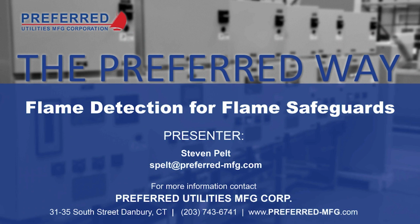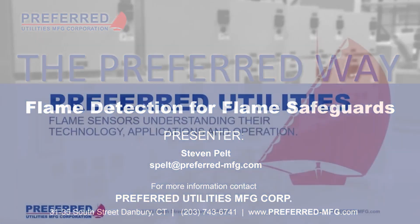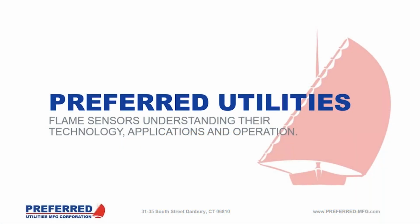This is on flame scanners, flame detectors, and flame sensors, if you will. Today I'm going to be discussing the different types and how they're used with flame safeguards in particular. The flame scanner is truly the main component of the flame safeguard system, and making sure that the correct type is used for a particular application is really the key to making sure that we have reliable burner operation.